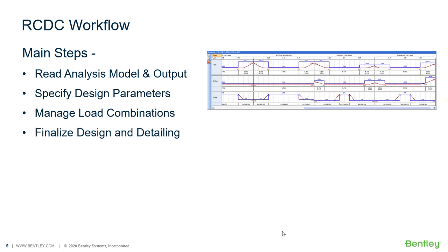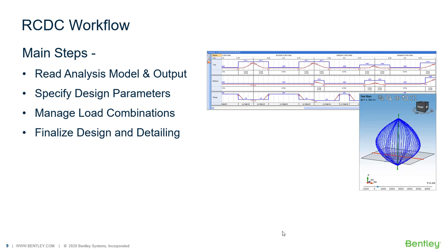It has a very interactive design detailing tool. In this case, for example, what you are seeing is the reinforcement provided and required graph for a beam, for the top, for the bottom, and for shear reinforcement. So it's very interactive, it's very graphical. Or this is a PM curve for a column, in 360 degrees, in ACI codes and so on.